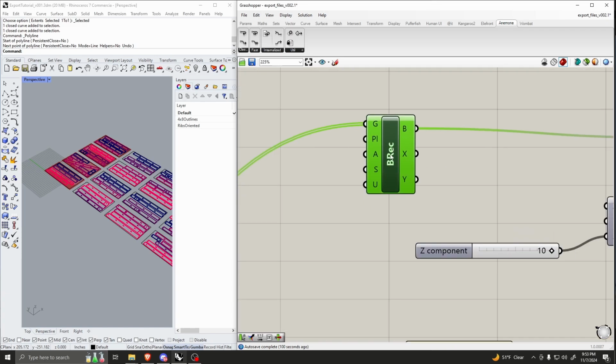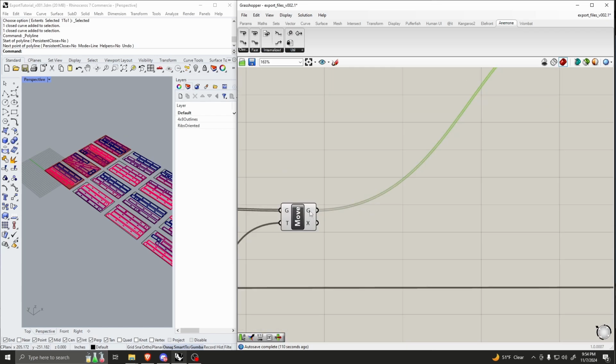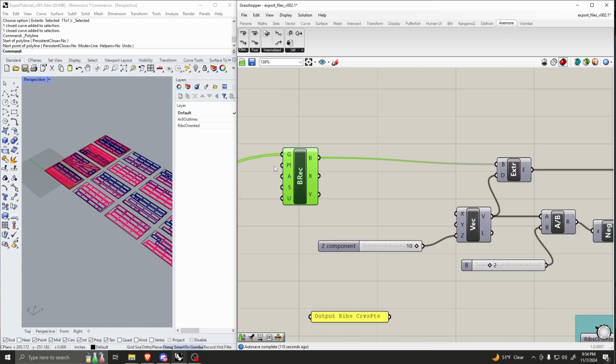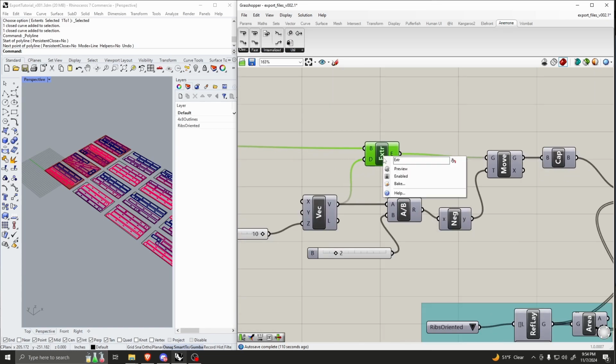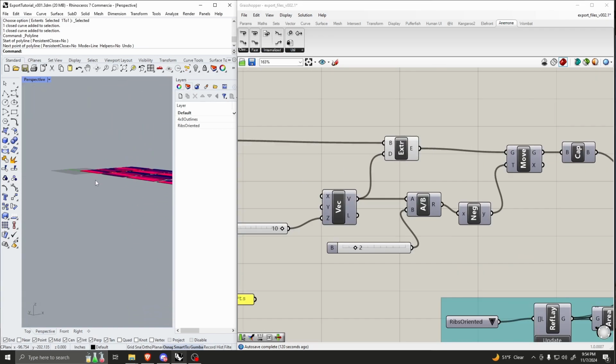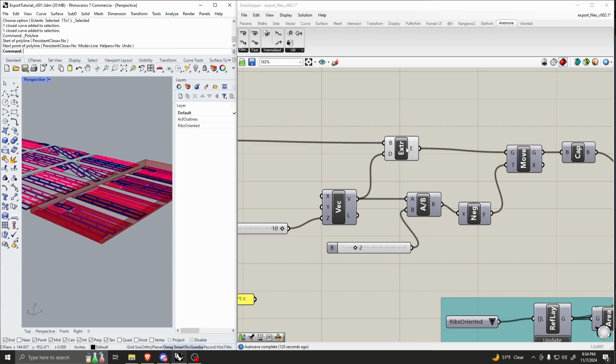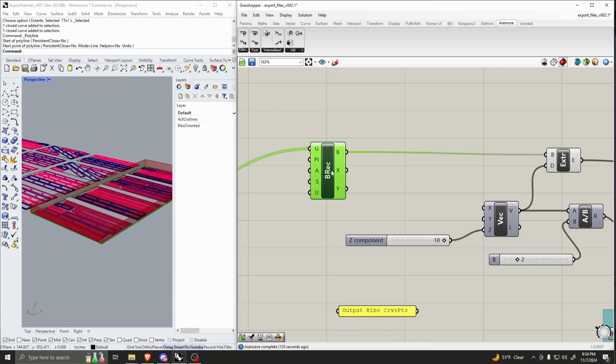Then what did I do here? I did a bounding rectangle. So this is, let's see here, 4 trims. Did a bounding rectangle. Then I did an extrude because I want to get a solid. Let me see here. I think it's on the last one. Yeah. So I did a bounding to get on the whole thing.